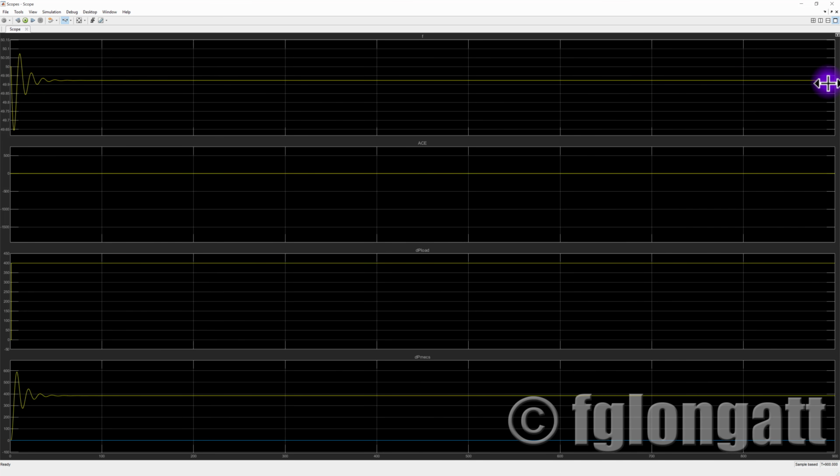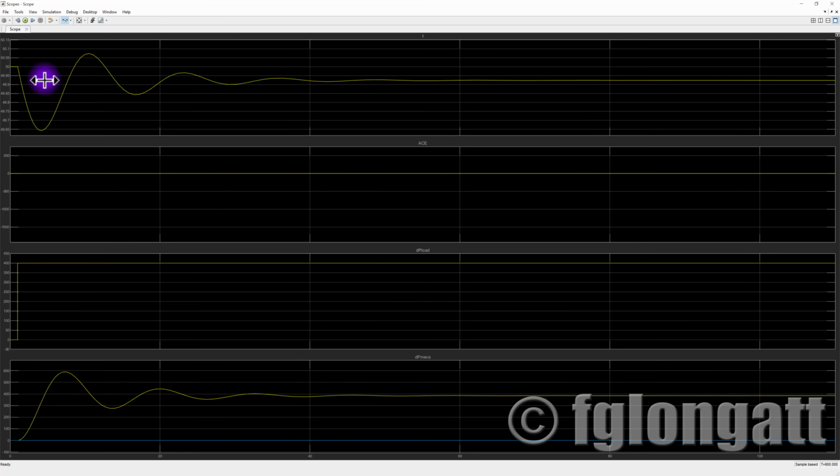As you can see, in steady state, as I said before, the frequency is not matching the 50 Hertz. In fact, this frequency is 49.92. Let me zoom in here around 100 seconds, okay? What you can see is that I use a 400 megawatt load change.